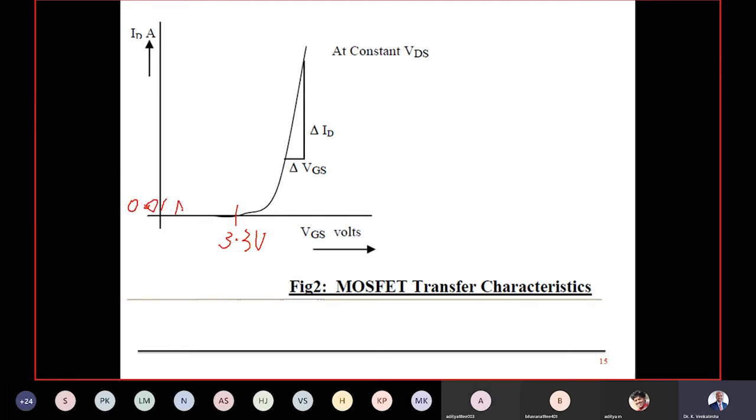0.01 amps. Further, you can go up to 15 volt. Then you can see current maybe around 1 amps, 1 to 1.5 amps. You tabulate all of them and rate a slope. When you rate a slope, already I got VGS threshold, which is very important for me.